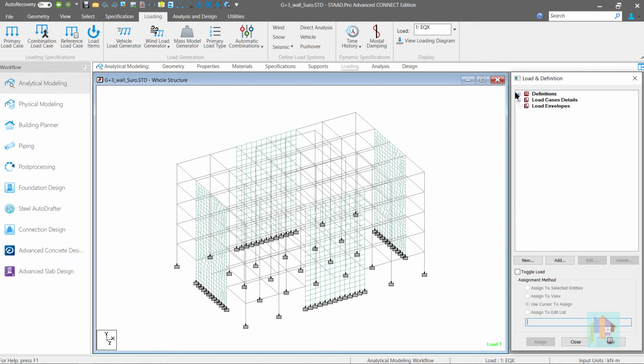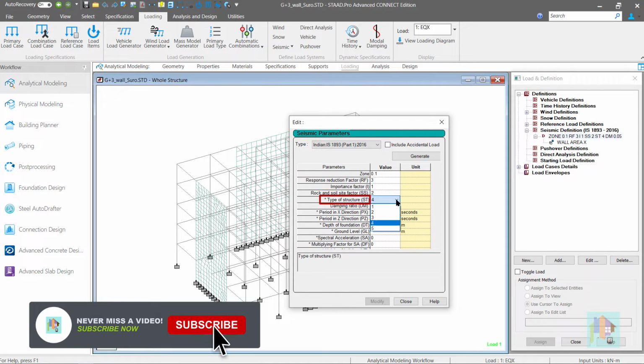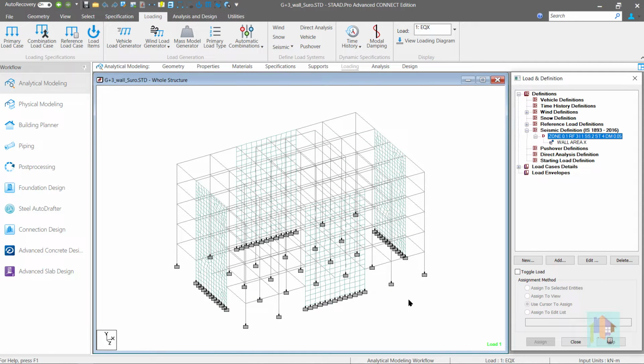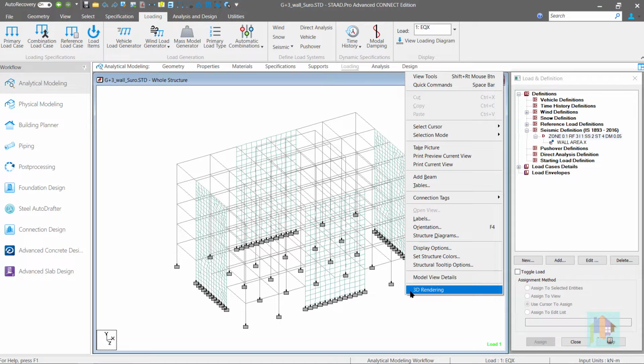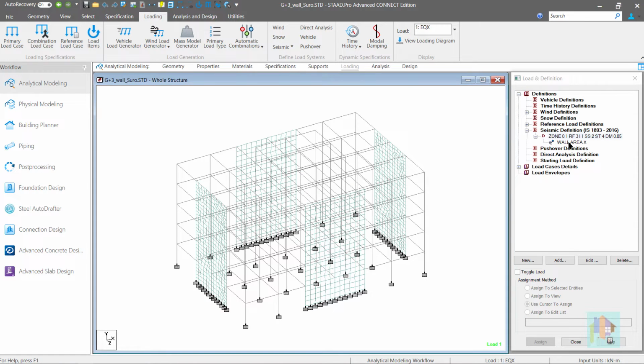I am Surajit Ghosh, and in this video, I will discuss the ST parameter in STAAD, how the time period of different structures is calculated following the guidelines of clause 7.6.2, and its impact on seismic analysis. Time period and structural behavior of a building with and without infill wall is different. How can we consider this additional stiffness of the wall during seismic analysis? That I will cover in detail.